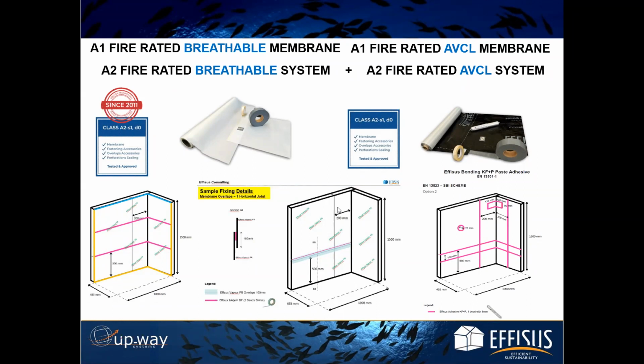And if you are selecting or specifying any material, what I advise always is that you look at the fire tests, you look at how the membranes and the accessories were tested. Everything was tested as a system, because this counts as a system at site.